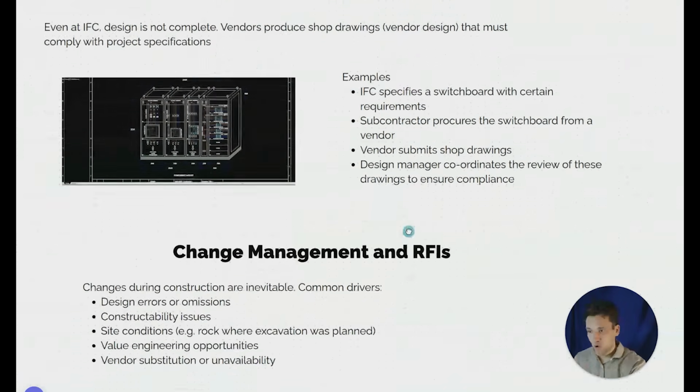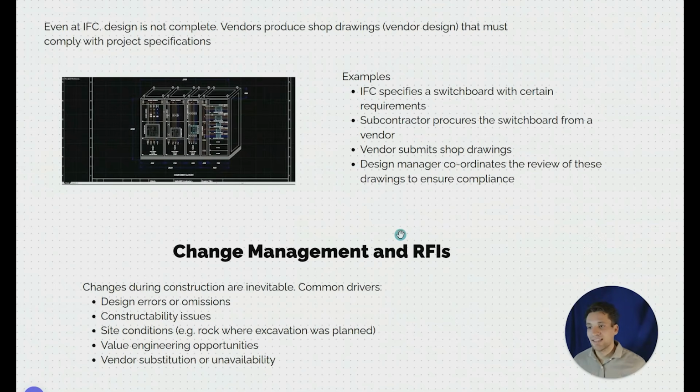Okay, so the next core role of the design manager during the construction phase is change management and RFIs, requests for information. So changes during construction are inevitable. There will not be a project without an RFI. Common drivers of these would be things like design errors and omissions. Maybe there's missing detail on a drawing, or maybe the set out height of a slab is wrong. Constructability issues, so things might not be physically possible to build. Site conditions may be different to expected.